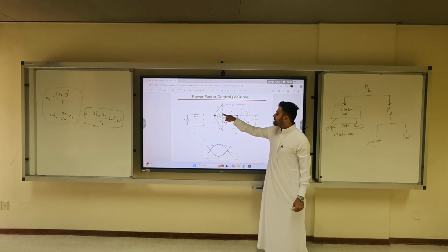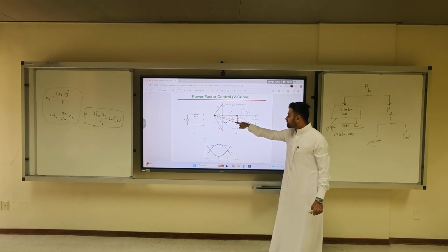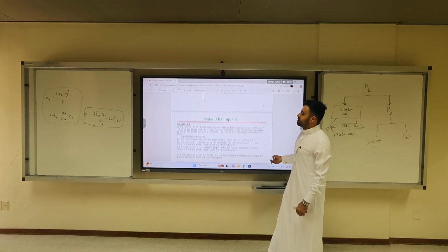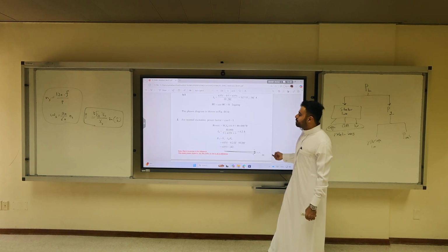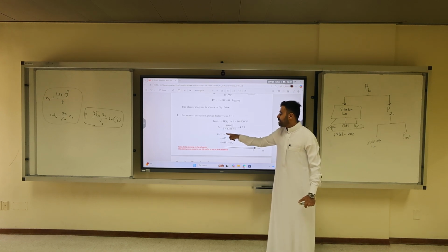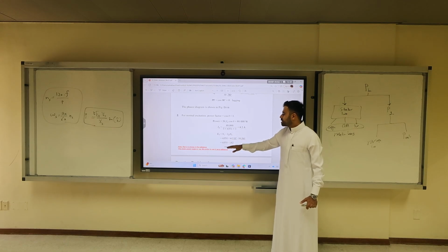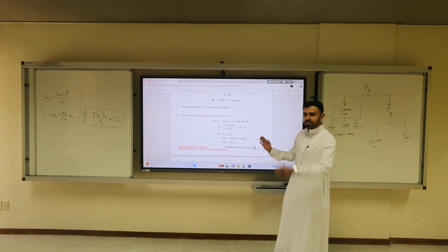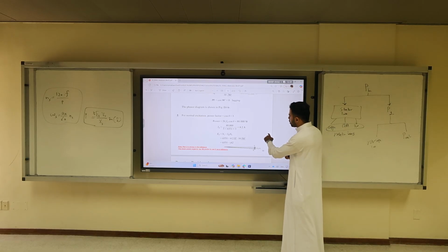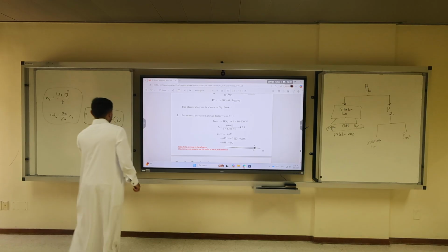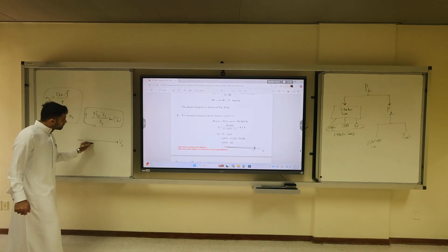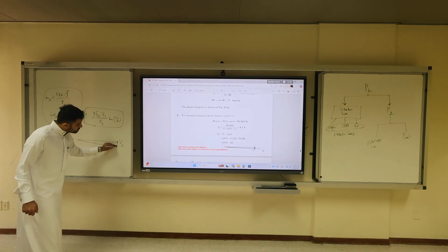So now if I'm normally excited with 4.2 amps, I'm going to get a certain EF, and I'm going to repeat the same for overexcited and underexcited. So how do we solve this problem? You have to calculate EF, which is VT minus jIAXS, which equals this number. Clearly, VT and EF now are not in phase. This is not a mistake, it's just rotated. I told you to draw it better: it's better to have VT at reference 0, and then EF like that.